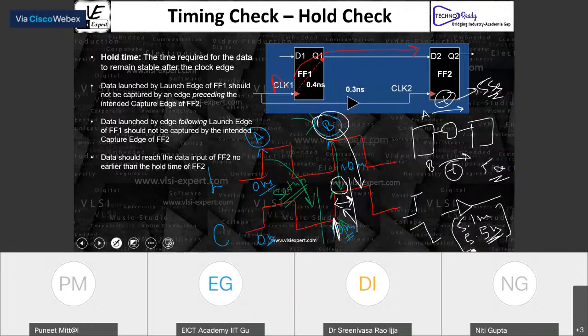That means now we are talking about two delays: one is 5.1 nanosecond, another is 5.5 nanosecond. So we usually talk about one minimum delay and one maximum delay. That means every cell has a minimum and maximum delay.